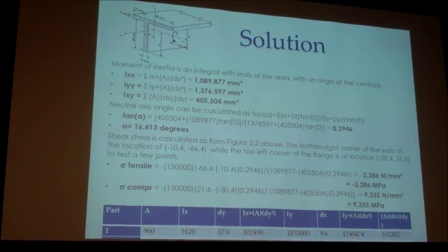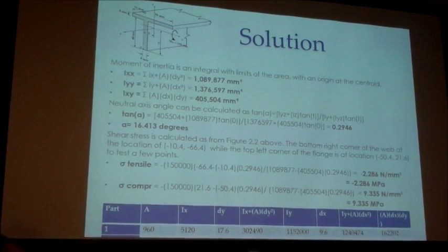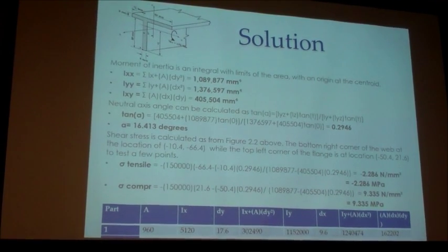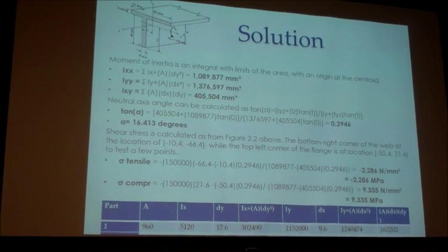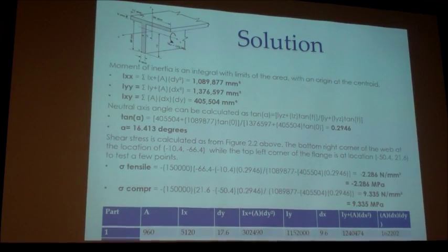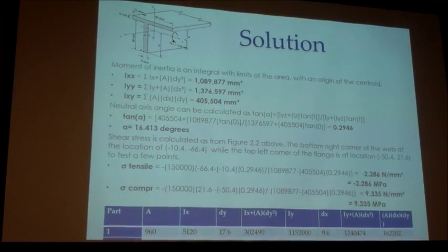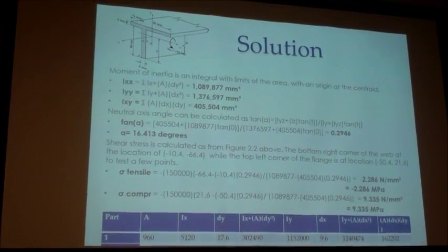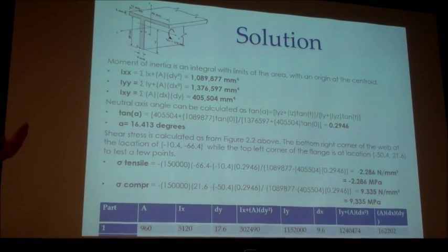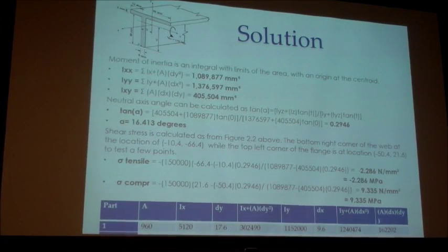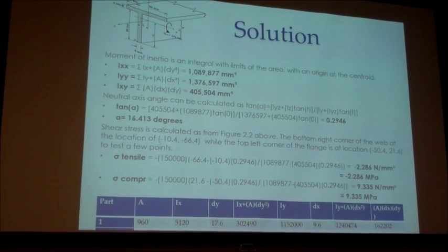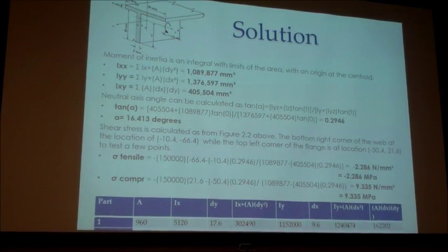So, on your slides you should be able to see the table. It shouldn't have been cut off. But we utilize that to calculate our Ix, Iy, and Ixy. And then from there, we have to now use this equation to find the angle for the neutral axis. It's actually from the horizontal x-axis, that alpha, and that's where our neutral axis is now skewed because it is an asymmetrical cross-section. I have it typed out there, but there is the pretty version on the equation slide.